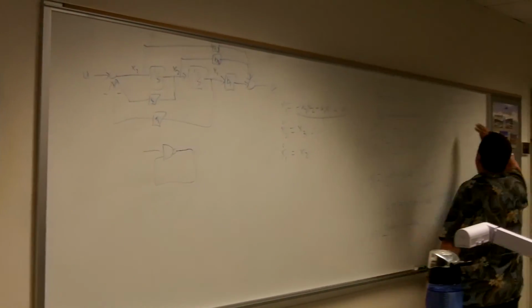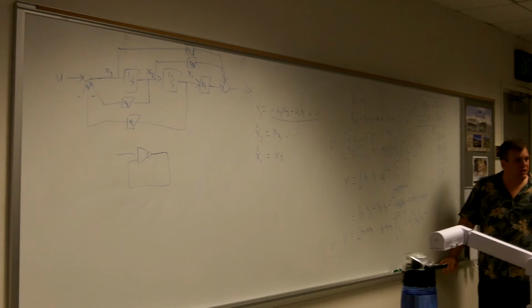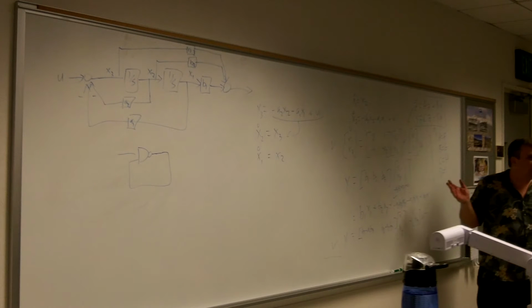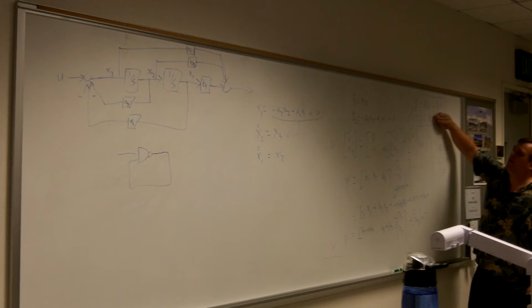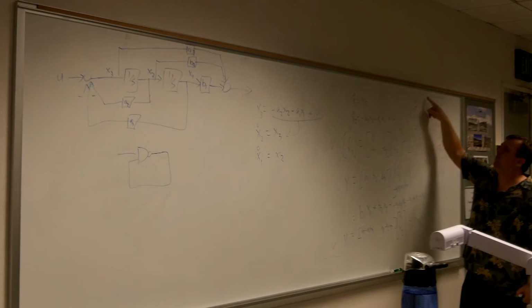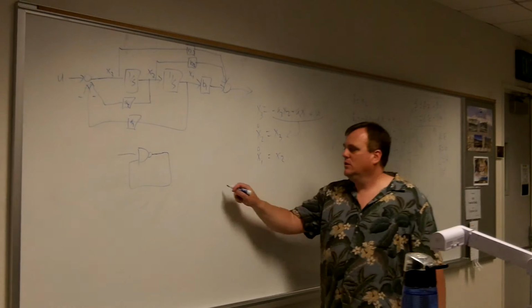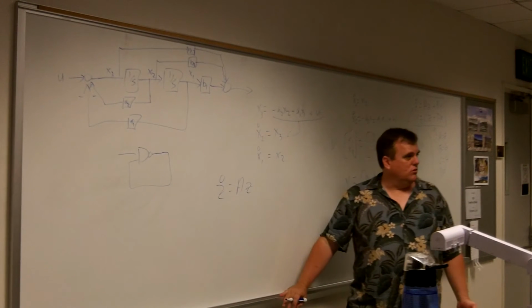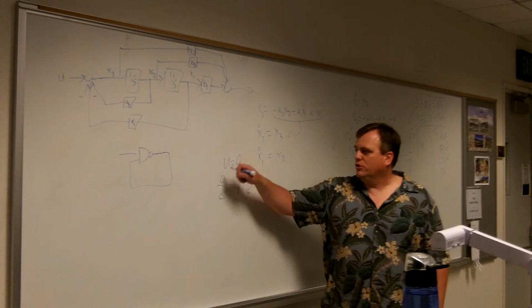So imagine for a sec that I turn the control off. I just said U equals 0. That's what we call the homogeneous system. Remember I said if you don't put an input to it, that's the homogeneous, that's how the system works on its own. So if I do that, those terms go away. And what I'm really left with is the interesting part of what's going on. Z dot equals AZ. Fair? Okay. So I've set U equals 0.